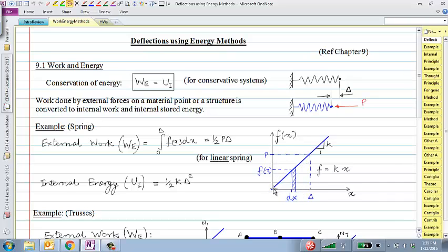But we are not really applying a total force P up here at the starting. We are applying force slowly as it climbs up. So the total external work done will always have that half in there. Make sense? For static problems that are loaded slowly, that half will always be there. Half times P times delta. That's the external work done on any structure.